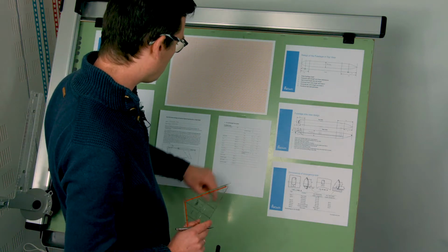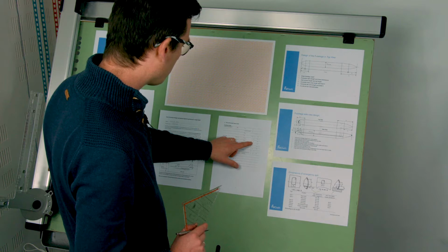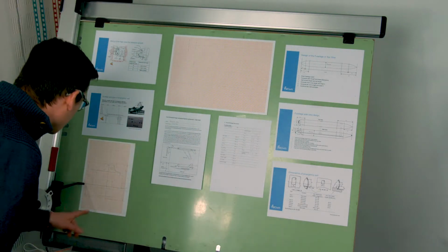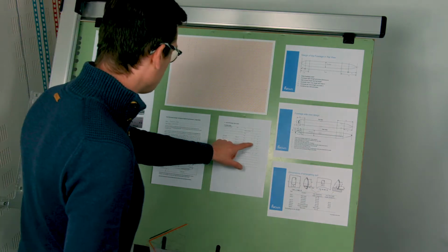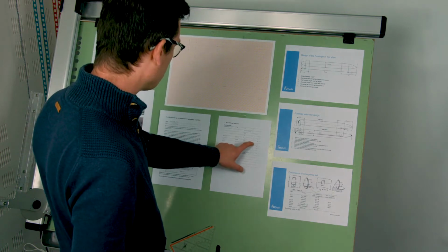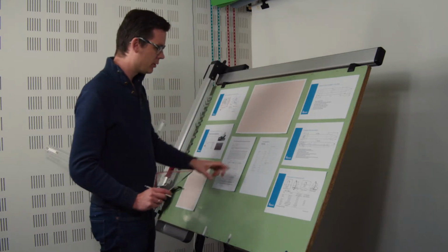For example, the outer cross section of this airplane is 3.4 meters. That's stemming from this design here. It's a little bit larger here, so there's a small discrepancy between what you have drawn and what I've actually computed. But in the drawing, that will come down to basically millimeters.